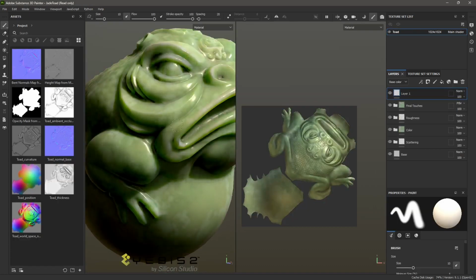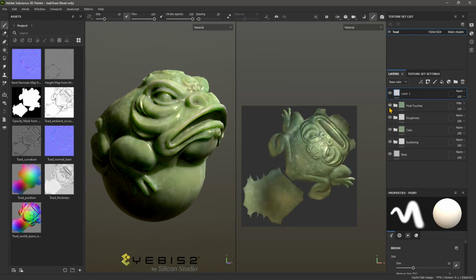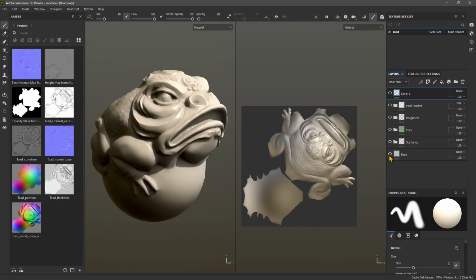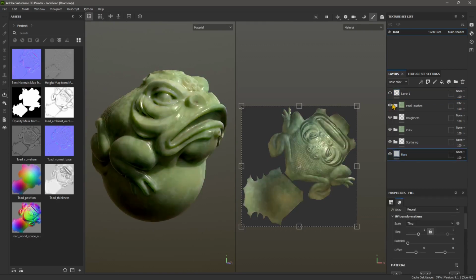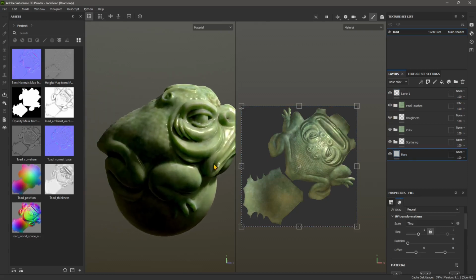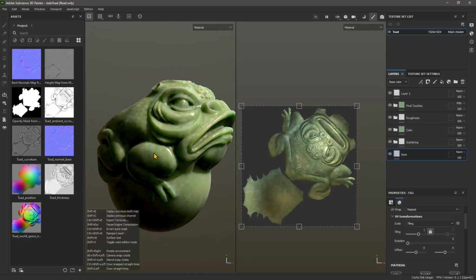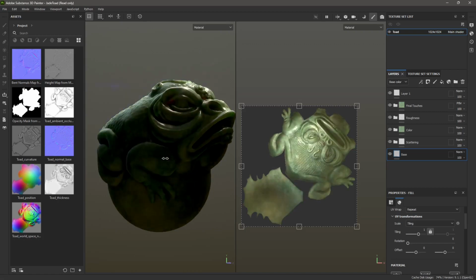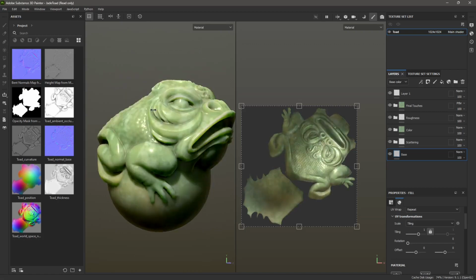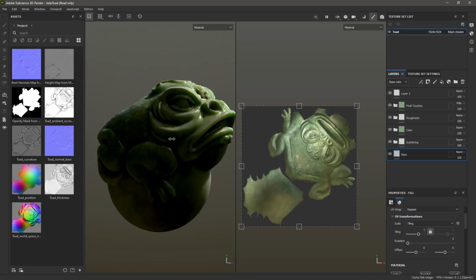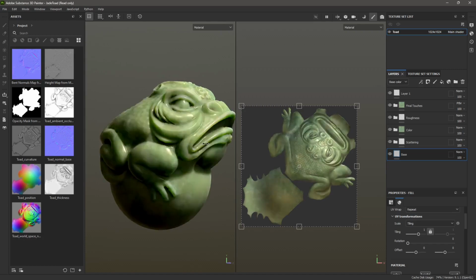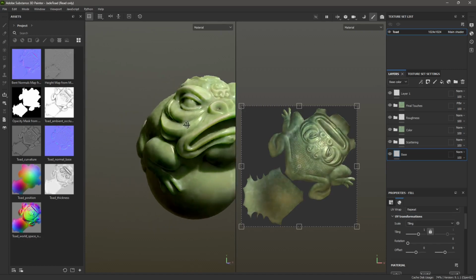And also here we have a lot of effects overlapping each other. So you can see here, you can turn them on and off to see the starting point. And some of these are baked. Baking means that, for example, if I have shadows, I can bake them onto the object. Now, if you hold the shift key and the right mouse, you can move around and you see also some lens effects there. You can move around the HDRI or environment map, which is going to give you different types of lighting. Remember that normal maps, environment maps, they participate to lighting. So you can change the lighting, changing the position of the environment map.